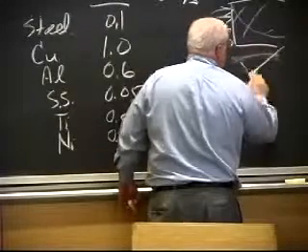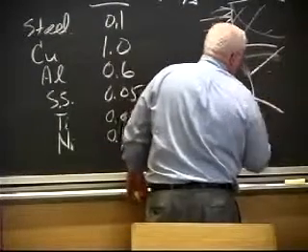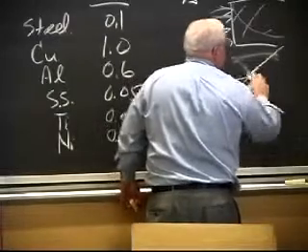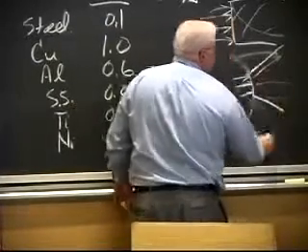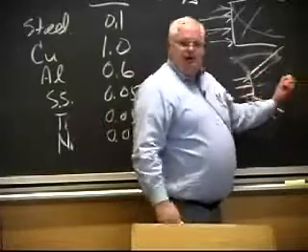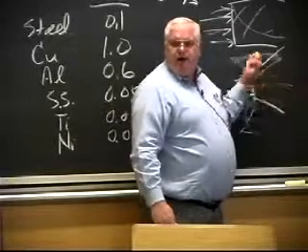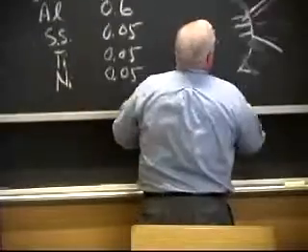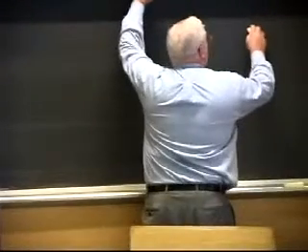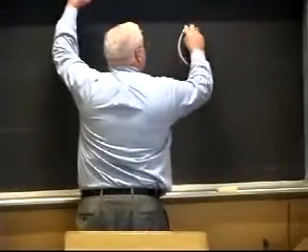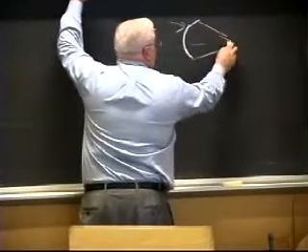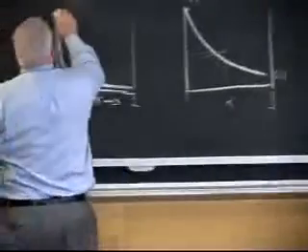I can have divergent heat flow where I'm applying heat to a curved surface and the heat has to flow out that way. Well, obviously that's not going to heat things as rapidly. My gradients are going to be smaller, right? I can have convergent, where if I'm heating a surface like this, but all the heat's converging, I'm going to raise the temperature more rapidly.